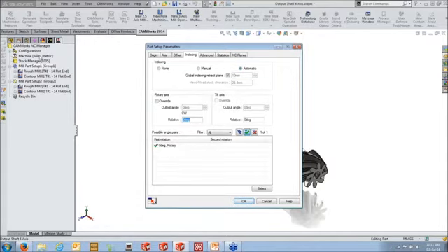And those machine limits that we set will actually filter out the different options down here. You might get a list of, say, 8, 10, 12 different solutions to get between the different setups. But by using the options set in the machine, it's actually going to reduce the number of these parameters and options for you. And then you hit select, and that will control your indexing for you.